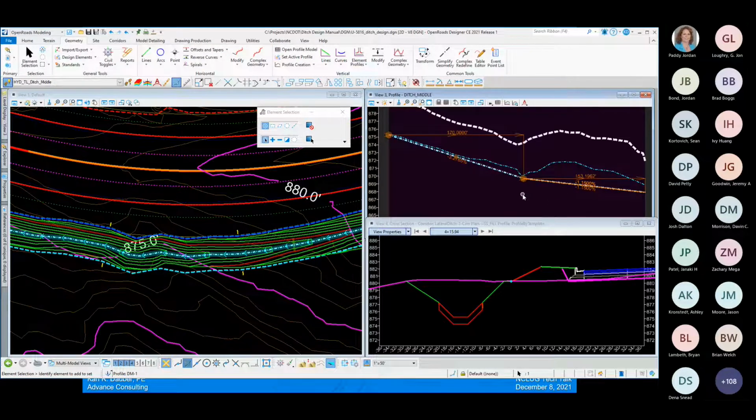It's typical for OpenRoads. You have a graphic manipulator here. I can simply grab that and graphically place it. There are some arrows here. If I select a left arrow, it'll hold the outgoing slope and change the station. Grab the arrow on the other side, it'll hold the incoming slope and change the station. I also have a number of text manipulators that I can click on and key in different values for station, elevation, and slope.